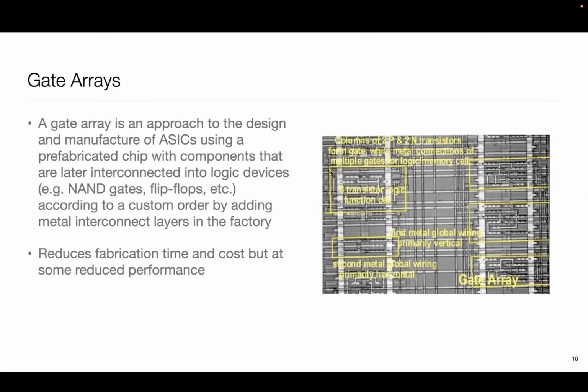Essentially, someone manufactures a piece of silicon where they put lots of transistors or small functions around transistors, like logic functions, AND, OR, those kinds of things. And then you have the luxury of wiring them up. The gates, or transistors, are baked into silicon, but the wiring hasn't been done, so we wire them up. Your design is really about whatever algorithm you think of, you now have to translate that into a custom wiring of the gates that already exist.